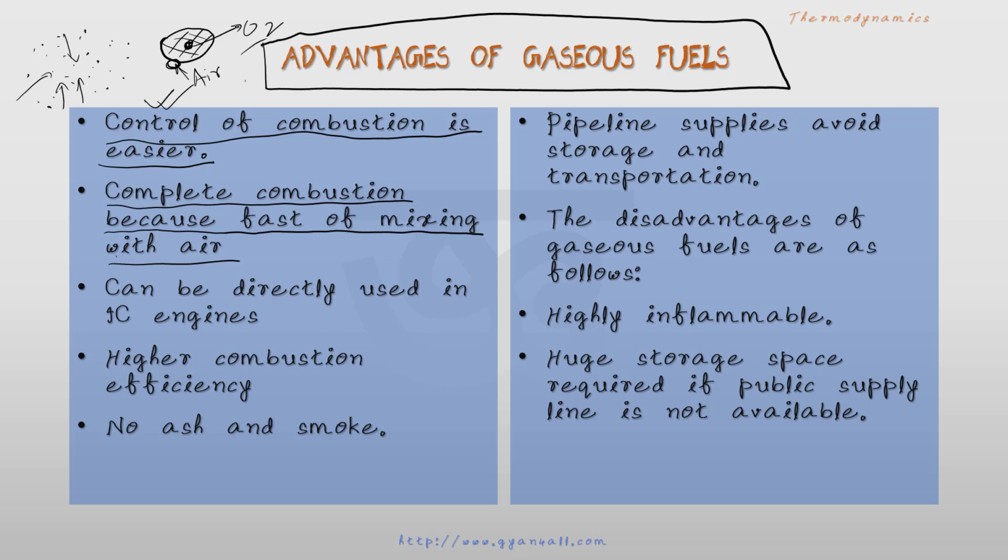And that is why we do pulverization. What is pulverization? Powdering of the solid fuel. If we powder it, then oxygen can reach each and every particle easily. That means complete combustion is possible.